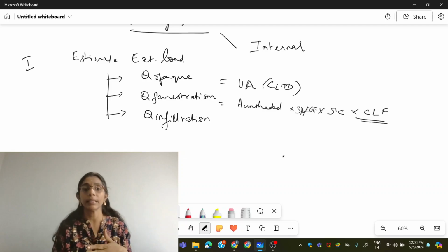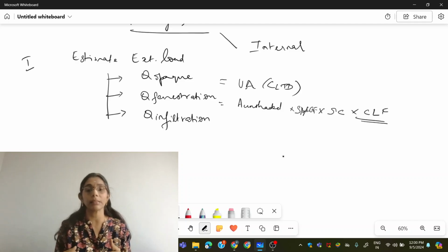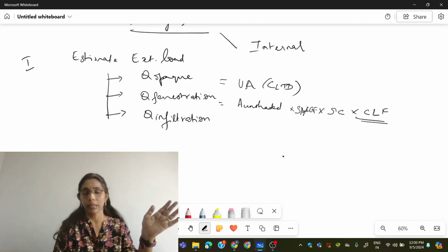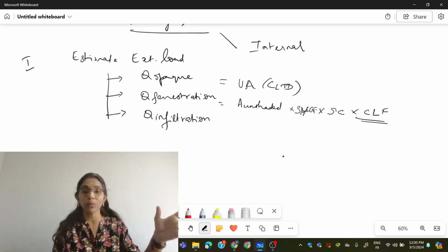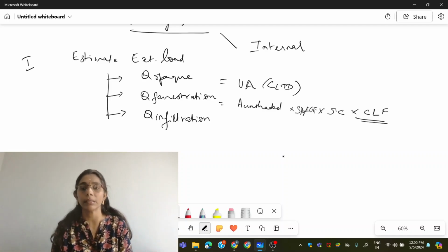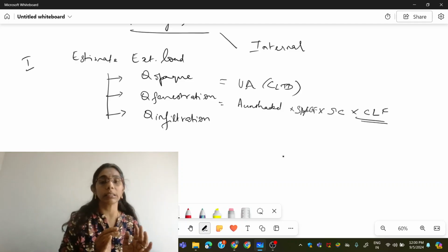I'll tell you what it is. Imagine the radiation that is entering the building. Say 40% of radiation is entering your building, and all of the 40% is not being absorbed by the space inside the building. This 40% of heat is absorbed by the floor, the roof, the walls, and also the furniture, whatever is present in the room. These are different objects with different thermal conductivity, so based on their thermal conductivity, they can absorb the heat and after some period of time reflect it into the space inside the building. It means the room itself will be heated up.